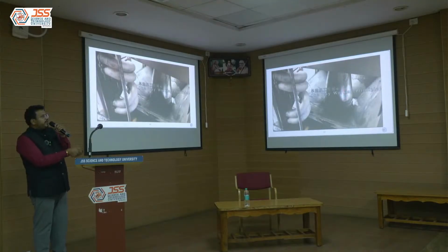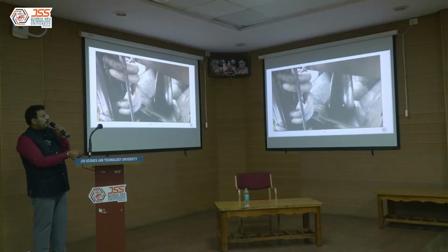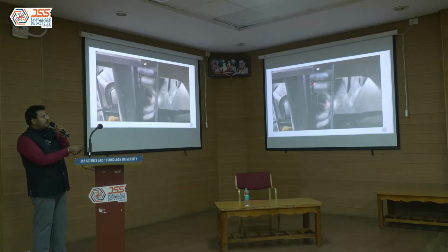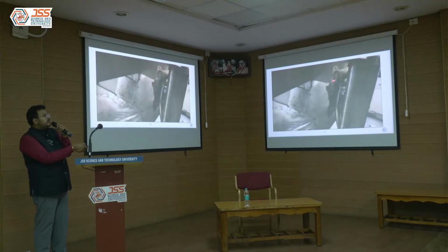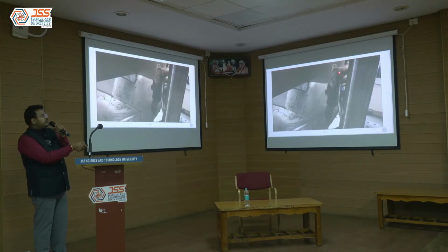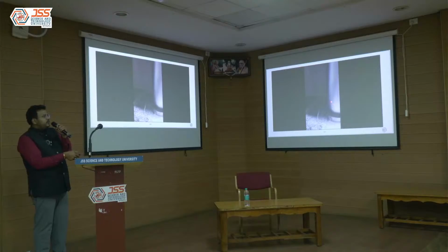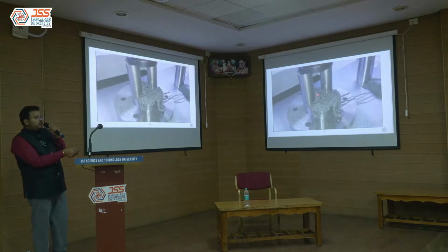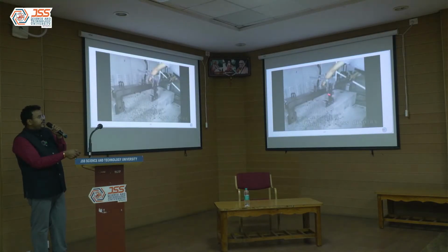So we are applying hydraulic pressure in the flexible tool, and the flexible tool or the media is coming out from the workpiece. This is the workpiece here, the manifolds which are used in automobiles. While traveling, it is finishing, deburring and radiusing. You can see here, the media is coming out from some complex geometries, micro holes, micro drills, and the media property is reliable in nature.